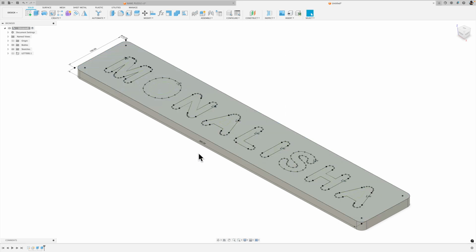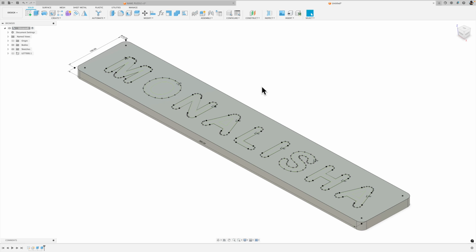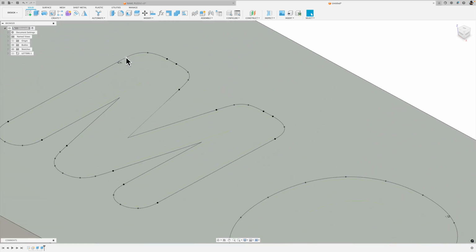Click OK. And notice that the sketch is now visible at the top here, and it makes it easy for me to go ahead and create this feature. And that's why I've negatively extruded. Just makes it a little bit easier. We saw in a previous video that you can click through bodies, but this way I'm just going down in the negative value. So now I'm going to go ahead and press E for extrude, but this time the extrusion operation is going to be a cut.